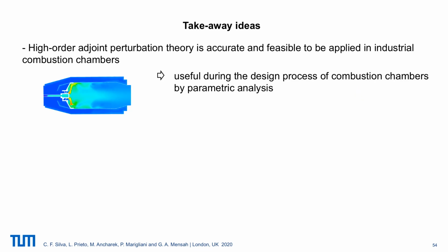Now we are in the last slide. So, the takeaway ideas. We use high-order adjoint perturbation theory to show that we can have accurate thermoacoustic maps in a very affordable computational manner. These kinds of thermoacoustic maps, when they are obtained from flame response models, can be very useful in the early stages of design in combustion chambers.